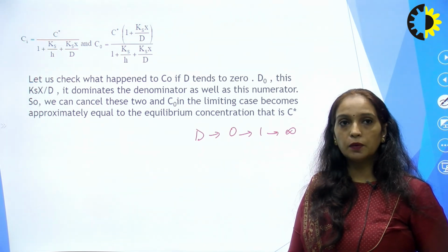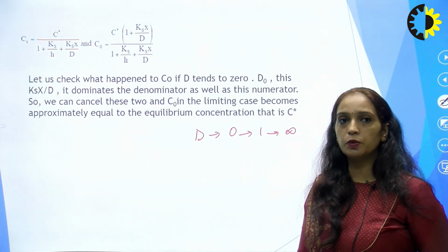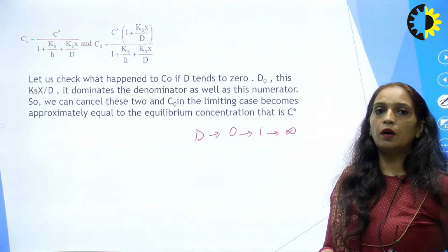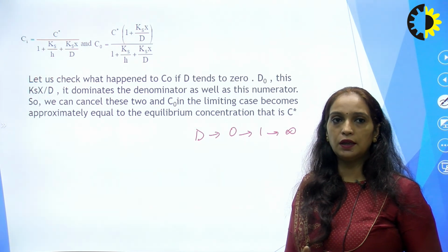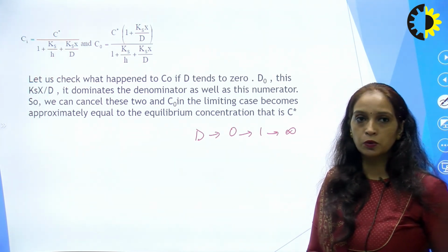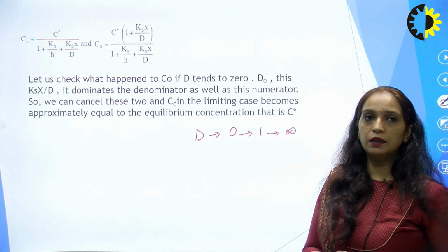So in today's lecture we got to know about oxidation, what oxidation is, how the oxidation process is carried out, which type of oxidation is better, and how the Deal-Grove model is used to calculate the kinetics behind the oxidation.